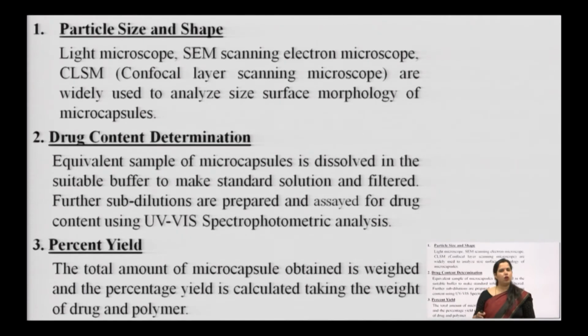Yes, you have a variety of methods of preparation for microspheres, right. So, you can then choose which method is giving what. Every method is giving different kinds of specifications, like spray drying will give you very fine small size particles, whereas coacervation will give you matrix type, and the air suspension method will give you higher size particles.